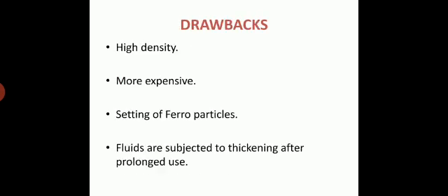Drawbacks. High density. Due to the presence of iron, these magnetorheological fluids are heavier. More expensive. Although being very much exciting, MR fluids are used in limited cases because of their high cost. Settling of ferroparticles. Metal particles tend to settle after long-term use. The last one, fluids are subjected to thickening on prolonged use, due to which replacing is required.